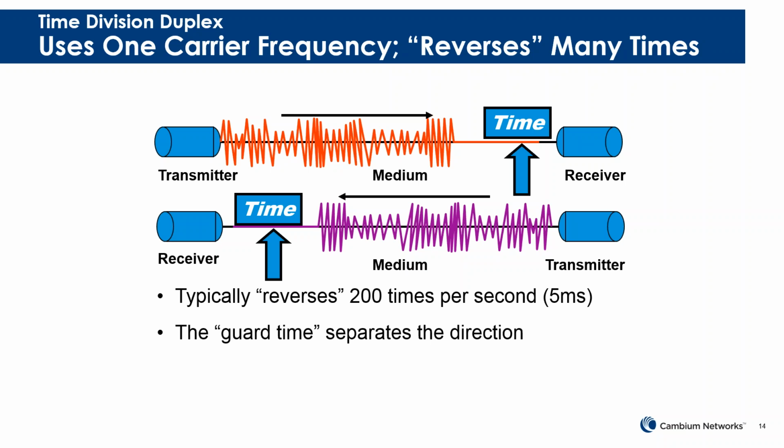And so you don't get these collisions that can cause retries, which then makes latency go up, as well as really impacts your ability to scale any type of radio solution, meaning add hundreds if not thousands of users onto that radio solution and think you're going to have any kind of meaningful communication with any of these devices if it's not scheduled.